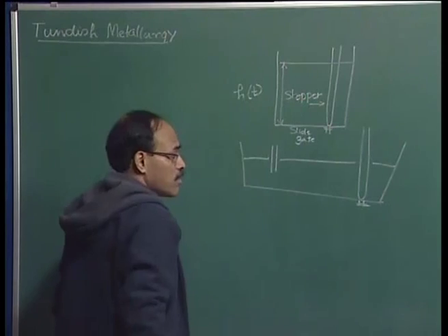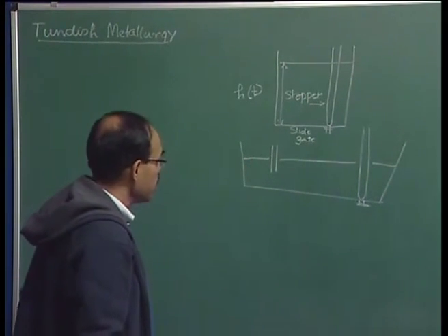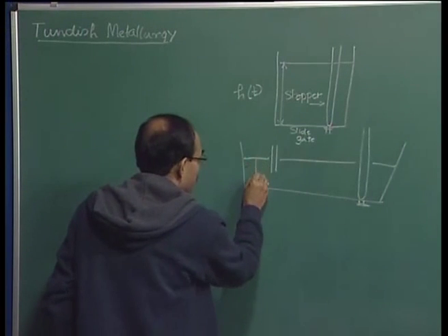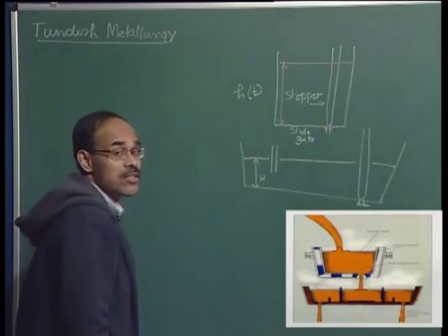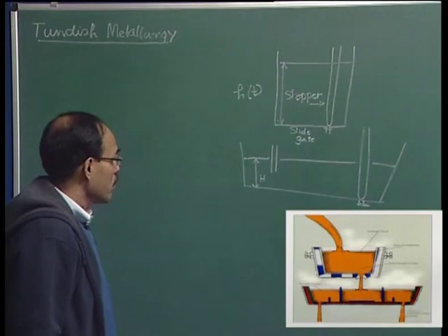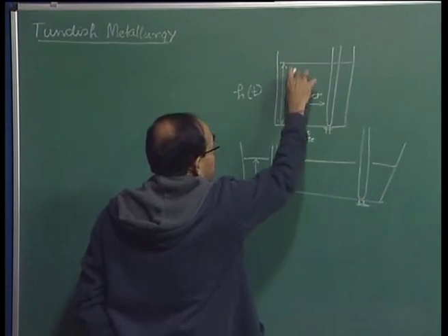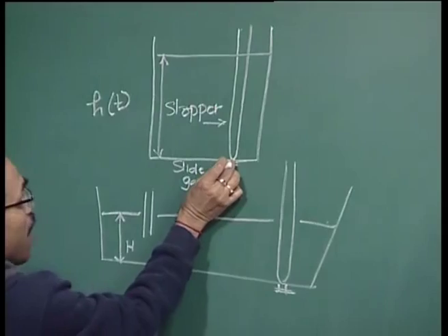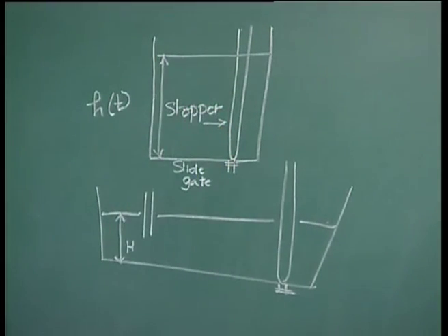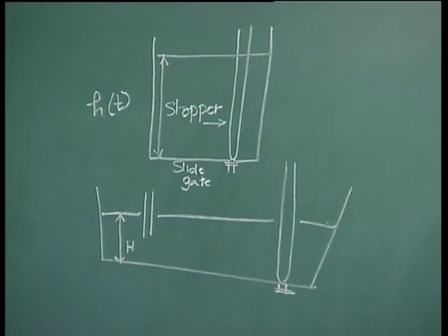On the other hand, except for the initial period of filling and the final stages of draining, as I have mentioned already, this height in the tundish remains constant throughout the process. Now, as the height decreases, normally for a constant diameter we would expect that the flow rate of molten steel through the ladle nozzle will also vary.